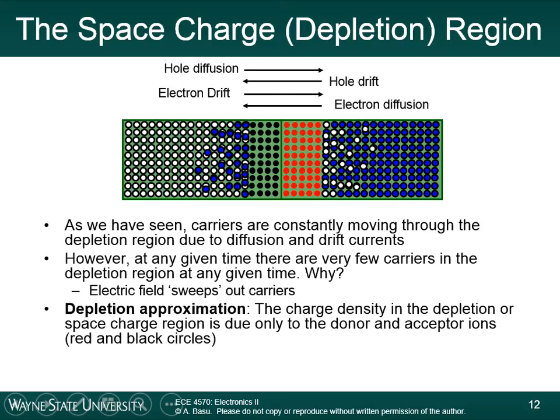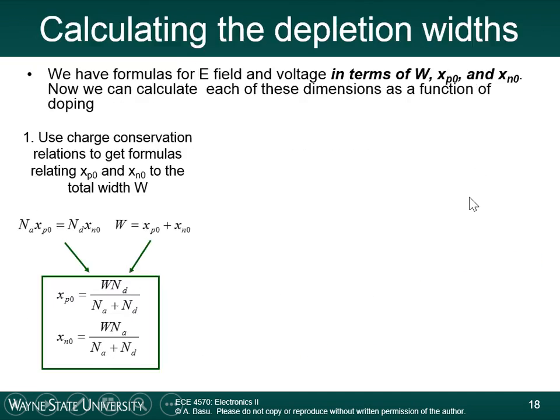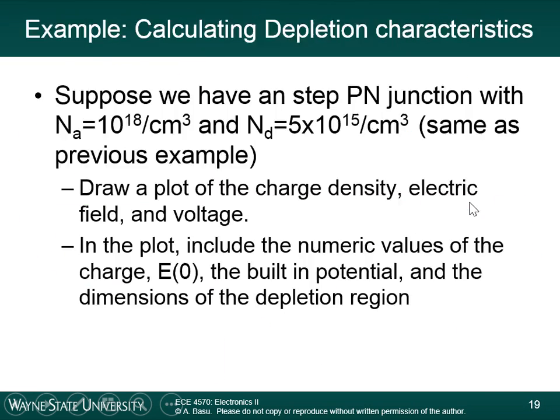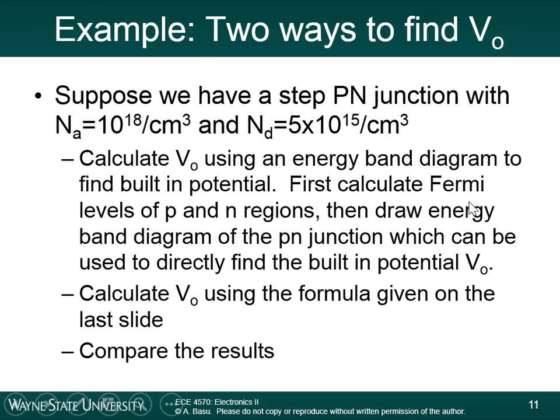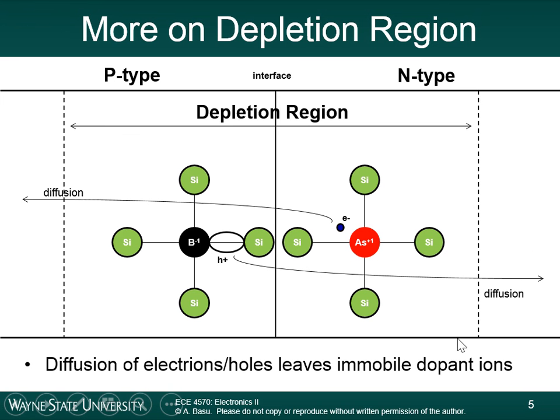Okay, and when the electrons diffused away this way, they left behind a depletion region, positively charged ions, and those were the positively charged arsenic or phosphorus nuclei that had a positive charge associated with it. If you remember, it looked like this. The electrons diffused over here, they left behind these positively charged nuclei. These are the dopant ions. And the same thing happened with the p-type region.